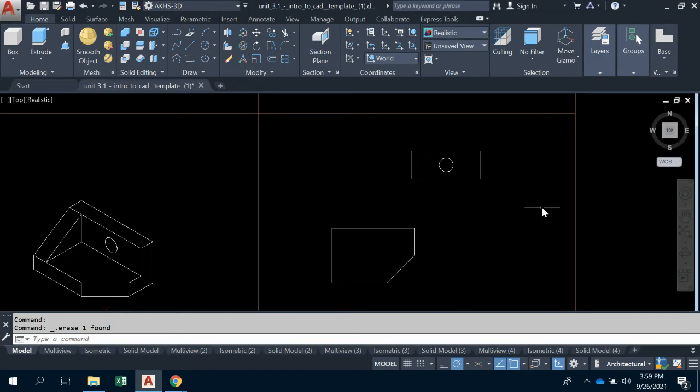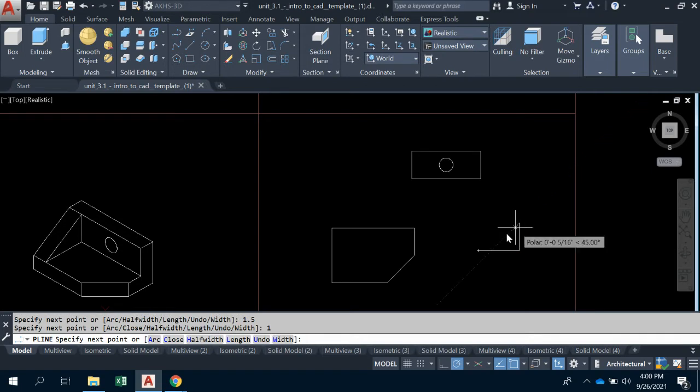And then the last piece is that triangle. So the triangle has a height of 1. Polylines again, remember that. It won't extrude correctly if you don't have polylines. Actually, I should have went the other way. We're going to try that again. So polyline, I'm going to draw the bottom first, and then I can connect the bottom. So the base of it should be 1.5. The height of it should be 1, and then it should connect here like that.